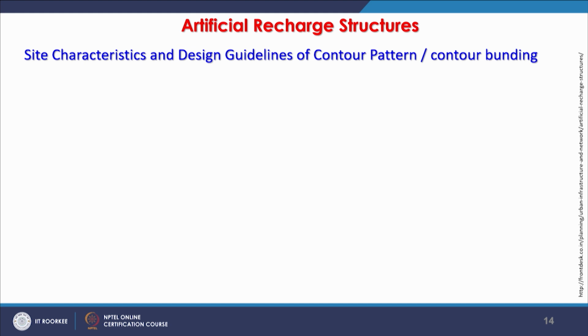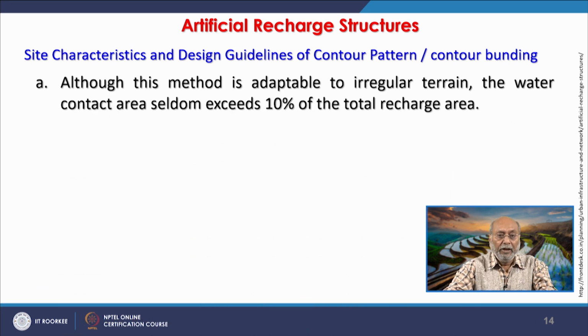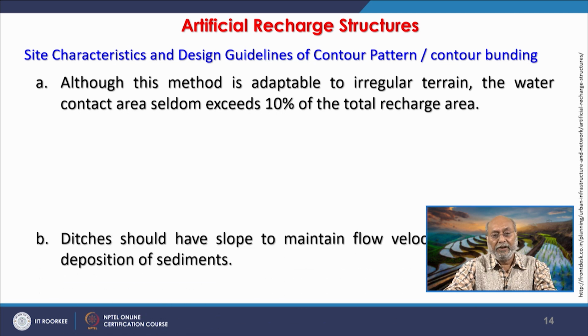Now we will see what the site characteristics and design guidelines are for this approach, that is, contour bunding. This method is adaptable to irregular terrain. The water contact area seldom exceeds 10% of the total recharge area.